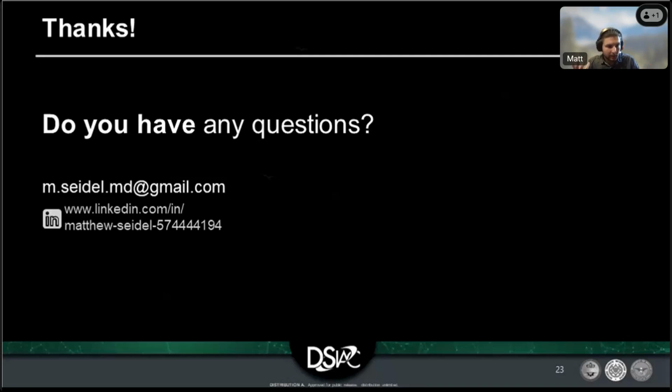And certainly some of the powder metal 3D printing stuff has touched equal or surpassed the strength. But with others, it comes down to almost a philosophical question: is it better to replace a CNC part with a metal 3D printed part for the sake of it? Or should I redesign that part to optimize for 3D printing? And then it's like, did I really need that strength to begin with? So it's a complicated question.